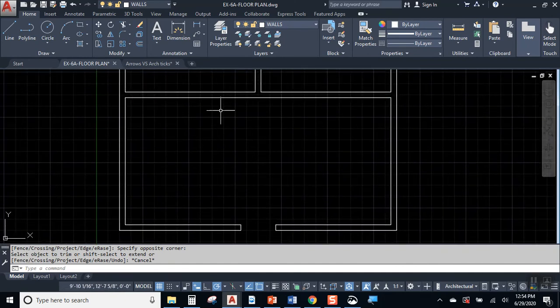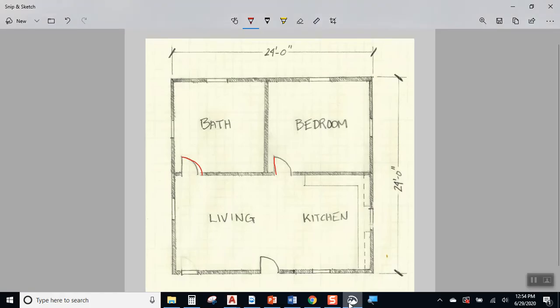Now up here and over here we have doors also. And we're going to have to talk about setting the door up correctly. Doors will never go exactly into the corner. There's always going to be a little bit of wall for the door to hang on to, for the jamb and the hinge to attach to. So there's this little ear of wall sticking out before the door begins. And that's the case here, and that's the case over here too.